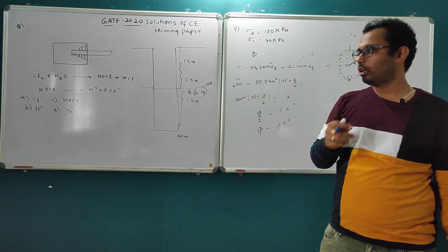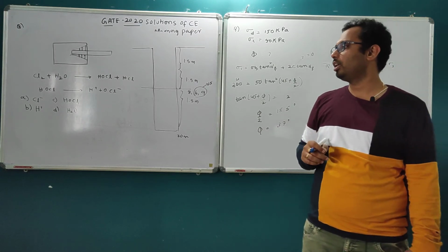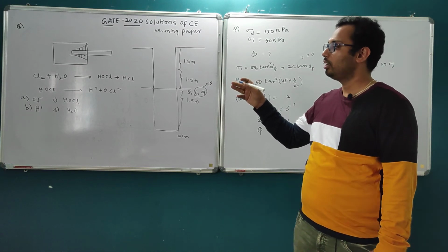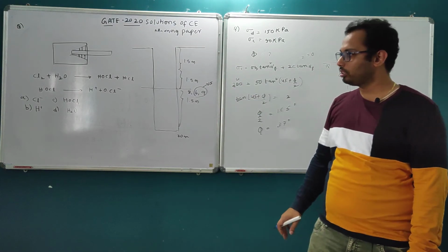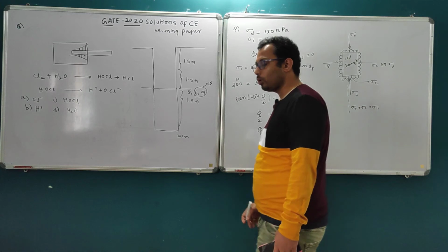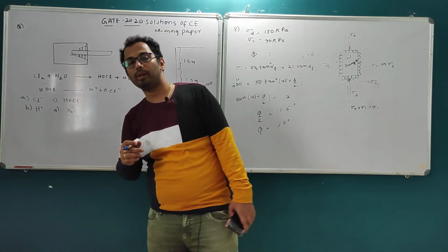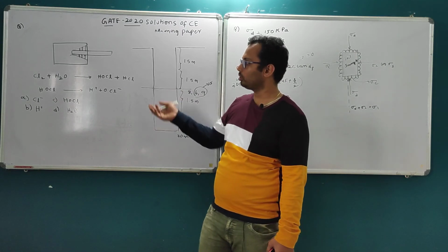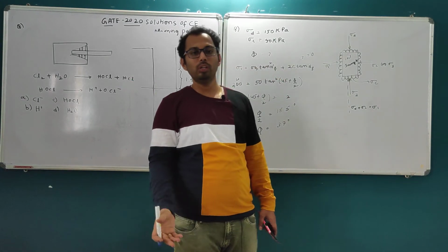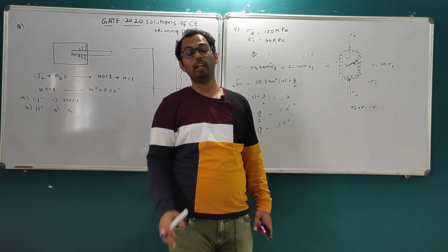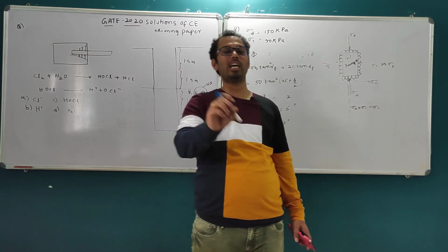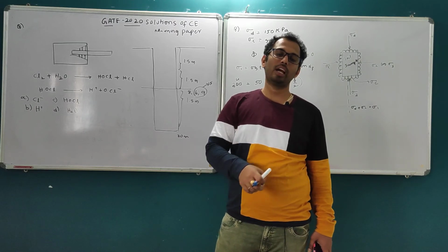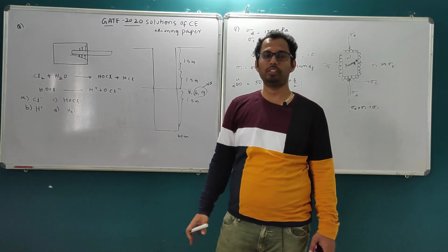So keep in mind that whenever there is a charge, why is OCl minus less effective than HOCl? We have studied that HOCl is around 80 times more powerful disinfectant than OCl minus. OCl minus is also coming from HOCl only, though it is a less active disinfectant because of its charge. OCl minus first tries to nullify its charge and then it starts doing the disinfection process.